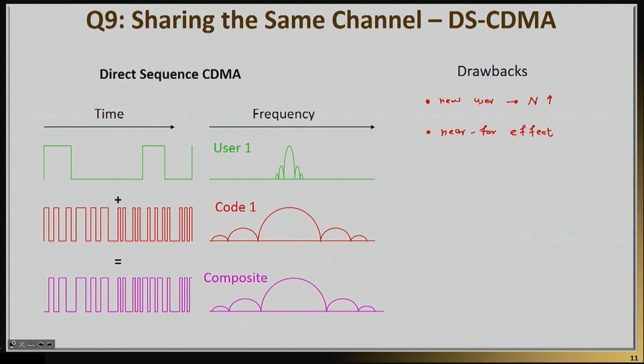Here's what I mean by near-far effect. So let's imagine the scenario of many mobile users. There's a base station. Let's say that I'm the base station. The person who is very close to me is actually transmitting a very large signal, while the person who is far away from me is transmitting a very weak signal. That means that the noise that we talked about here, added by the loud user, is actually far worse than the noise added by the far away person. And so what happens in those systems is that if somebody decides to either be very close to the base station or actually transmits very loudly, it will actually corrupt the noise for everyone. That's a very famous near-far effect.